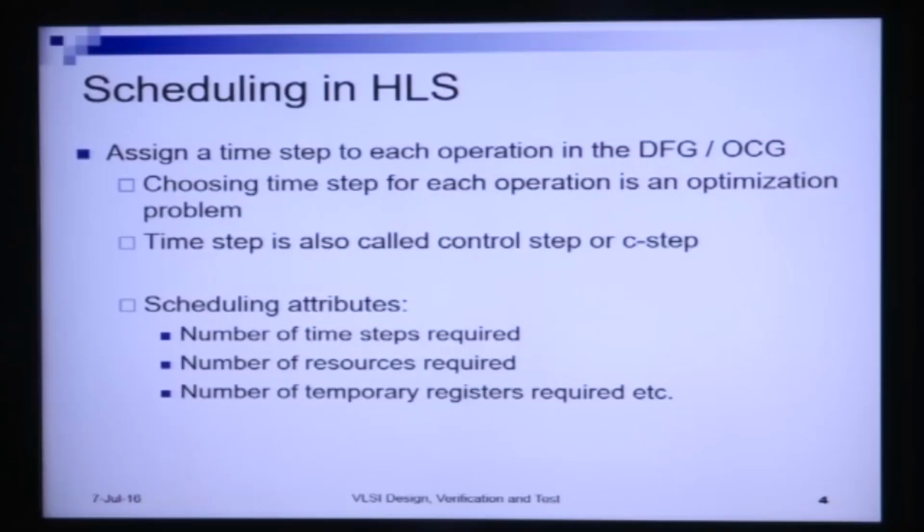So, scheduling is the task of assigning a time step to each operation in the data flow graph or the operation constraints graph. However, choosing a time step for each operation in general is not a trivial problem.